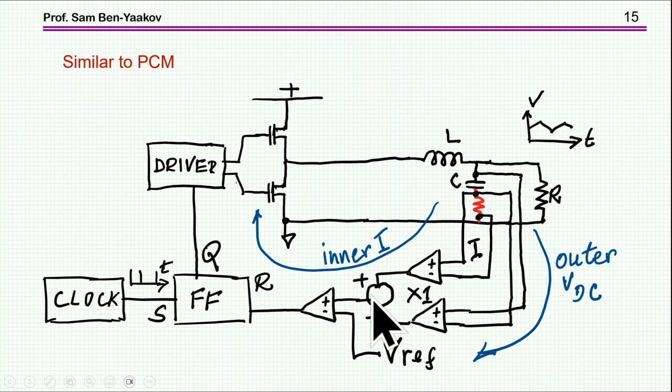And here is how it operates. I'm showing here the output voltage. There is again the 1 amp step load. You see that there is a drop, of course, due to the load, and there is a recovery, but as you can see, the average voltage of the output now is 5 volt, and once it's recovered, it's going back to 5 volt. Very, very neat. Now, this signal here is actually this moving reference.